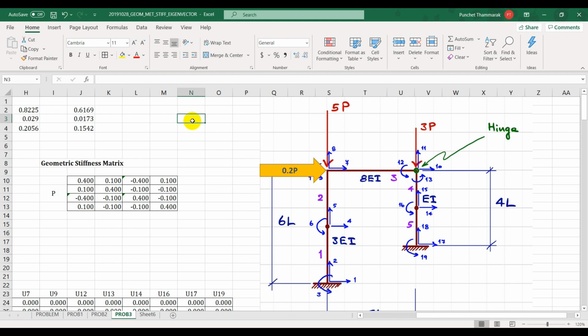But the best way to do all the things, at least this covers up your knowledge in the first part before the midterm exam, is to be able to construct the stiffness matrix of everything, and then you incorporate the geometric stiffness, and then you run this iterative solution until you get the nicely converged solution, and then you plot the corresponding displacement to one set of load.